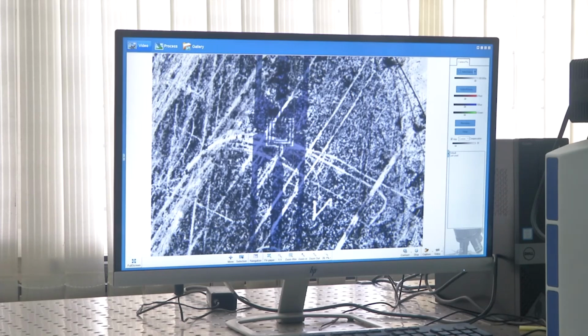If you look closely, you can see the electrode structure. On top of the electrode, we have coated carbon nanotubes. So this will act as a sensing layer. If some material comes and interacts with the carbon nanotube, it will change the impedance of the underlying electrode, and that can be used for sensing. So this is a course in sensors and actuators. That's why I am taking you through different interesting types of sensors and how they can be actuated in real world situations. So this is one type of sensor that can be used.